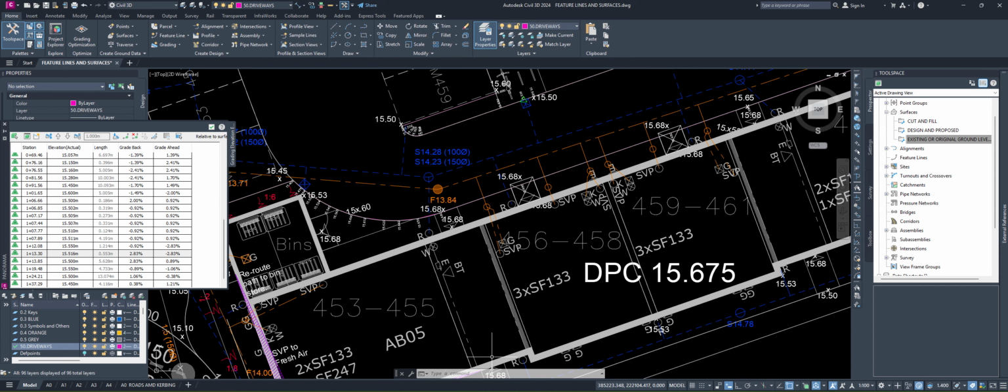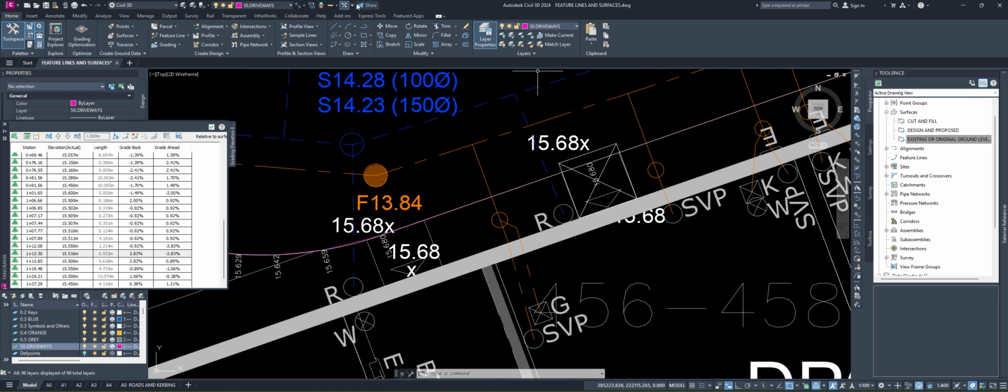So we don't want to create a sharp or too much fall where it's going to need more human force or power for a wheelchair to climb the ramp. We don't want to create a ramp. What we want to do is just slightly drop the edging line down, plus it's going to help the water run along the channel.